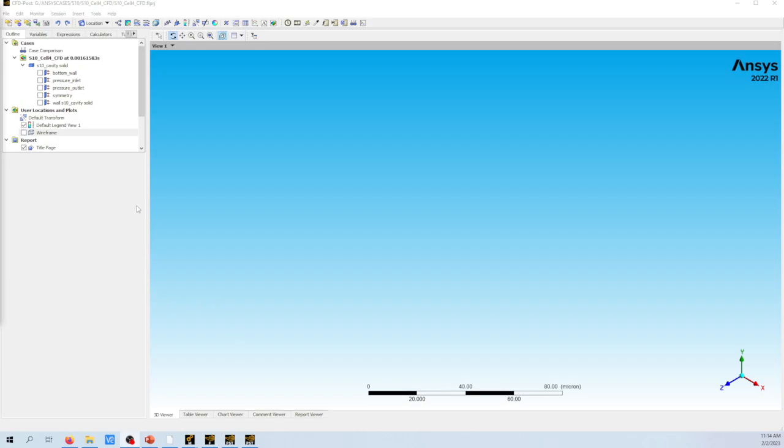Now that we have our results, something also I would like to note about our results. By defining our contact angle, we have essentially defined a static contact angle. Now, this is a dynamic analysis, so that is a bit of an assumption, that the static contact angle is about the average of the dynamic. So just keep that in mind for this as one of the limiting factors here.